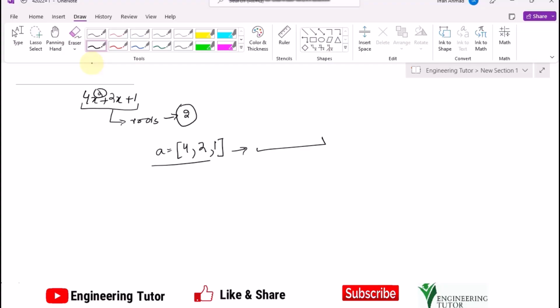Similarly, if we have other types of equations as well, let me have 5x to the power 4. In order to convert it into the MATLAB vector, we have to write here 1 0 0 0 0. This is the 4th coefficient, this is the 3rd, this is the 2nd, this is the 1st, and this is the DC term. These are the coefficients. We have 4 zeros while 1 coefficient with which the equation will be here. So here with x to the 4 we have 5. So instead of writing 1 here, we can write 5. After it we have to apply some function over it.